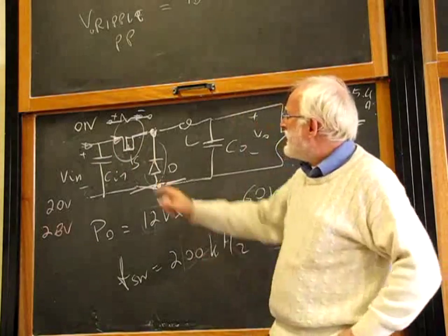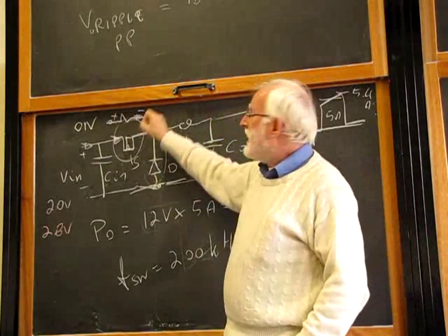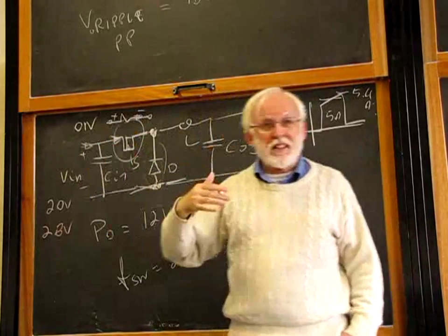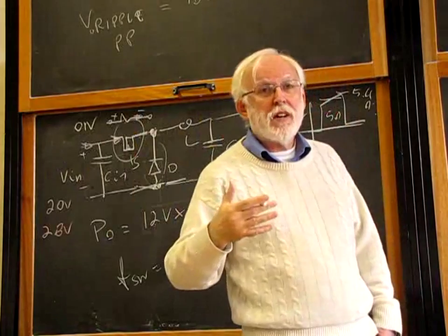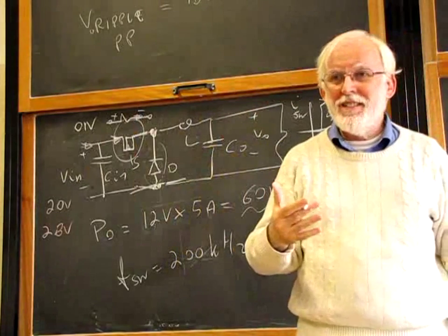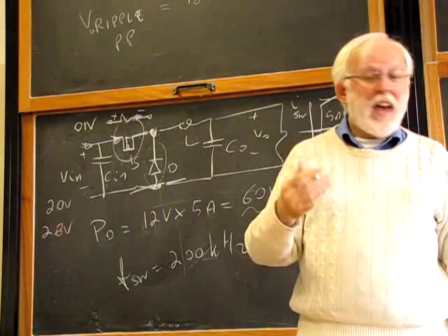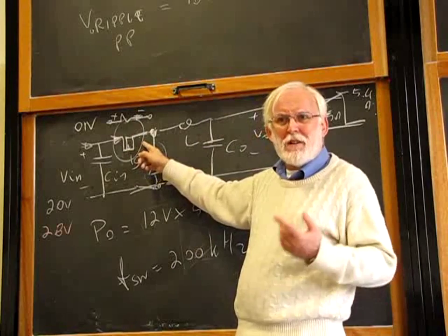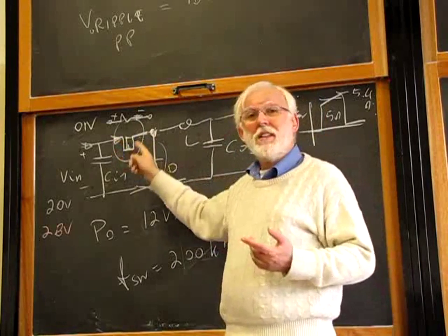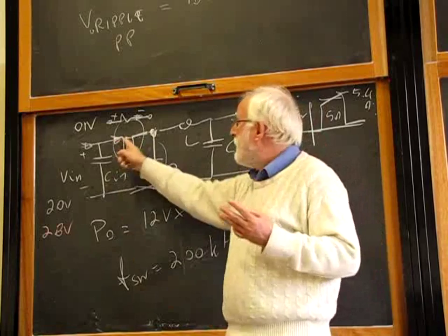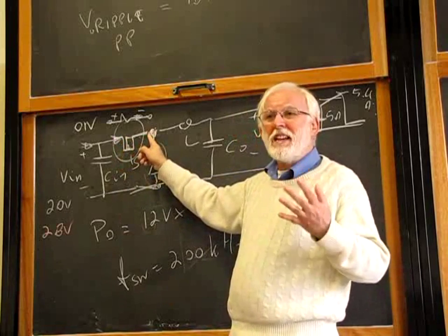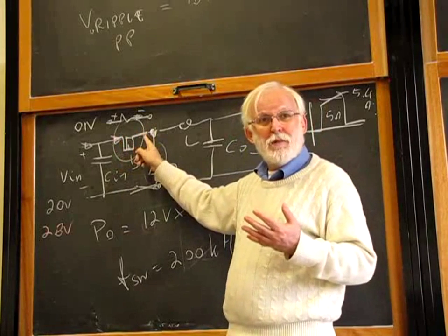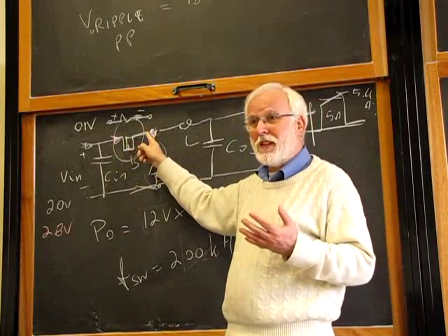But what is important is that this voltage drop is in series with the input voltage. This voltage drop is subtracting from the input voltage. So if your input voltage is 300 volts, just an example, and you drop 1 volt over here, that's okay, who cares? It's less than 1%. If your input voltage is 3 volts and you drop 1 volt over here, you are wasting 30% of efficiency just here across the switch. One third of your input voltage is lost just across your switch.